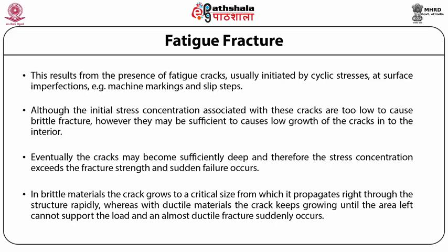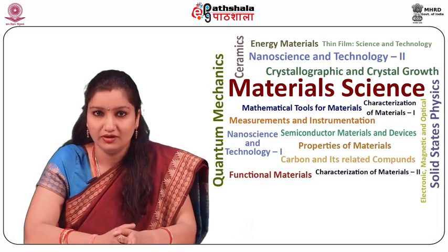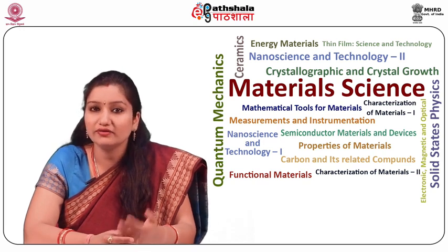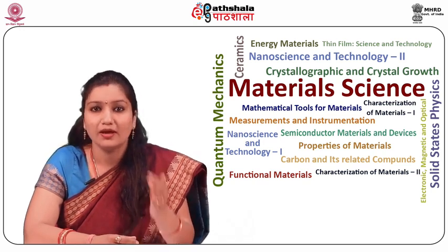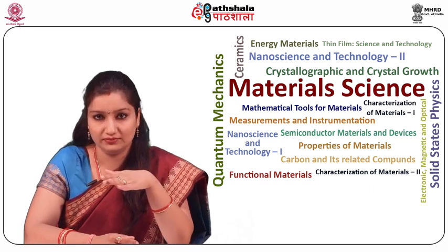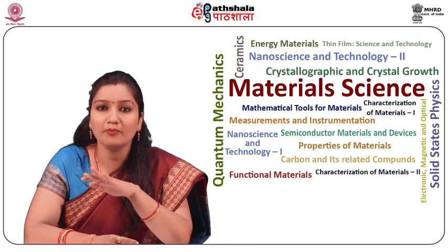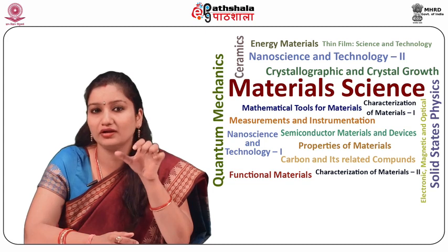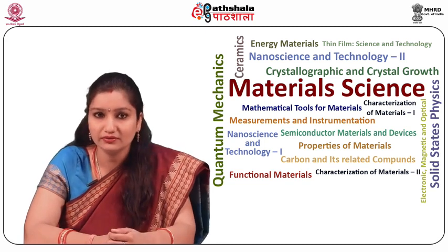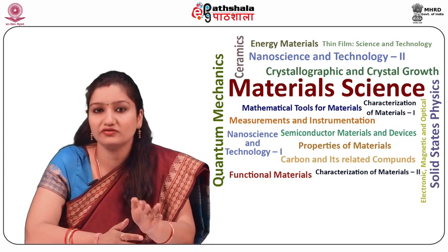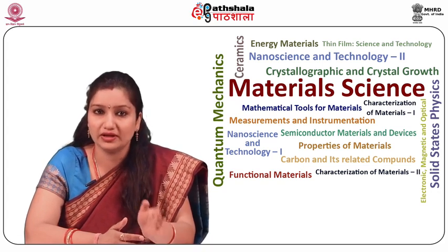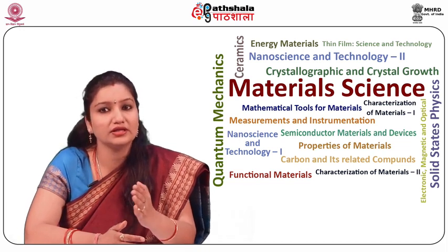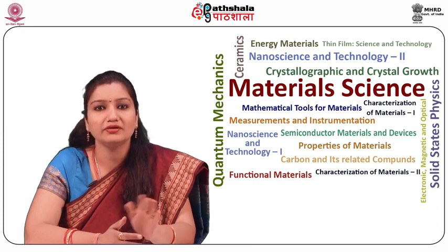Fatigue failure. Now we are going to discuss the topic fatigue failure. One can recognize fatigue failures by the appearance of fracture. Fatigue failure has a number of specific features compared with failure under static loads. Number 1, it occurs at lower stresses than the failure at static loads, which means lower than the yield strength or ultimate strength.